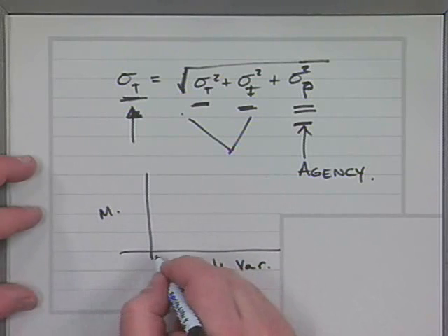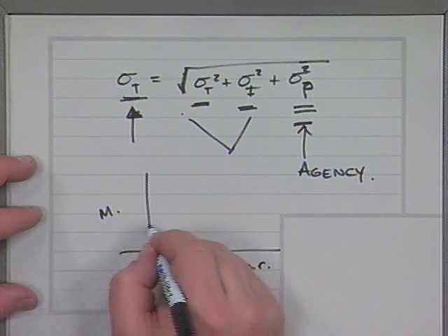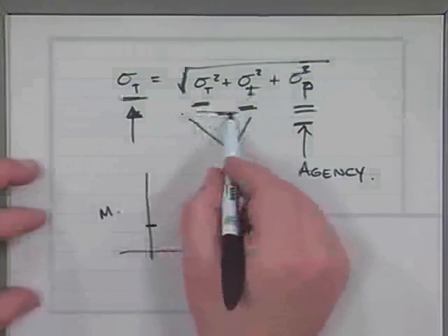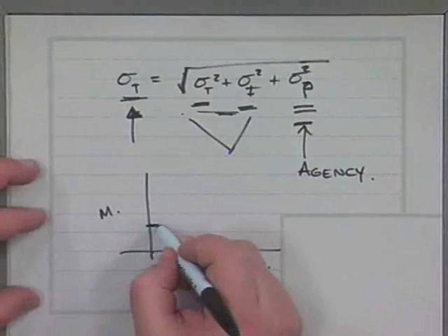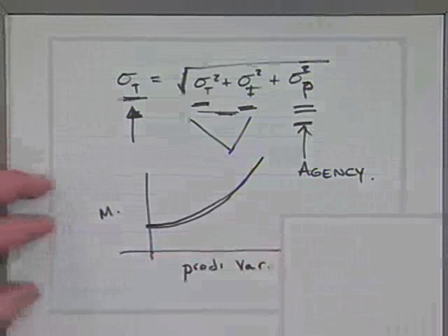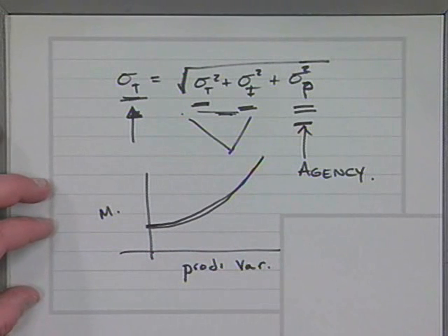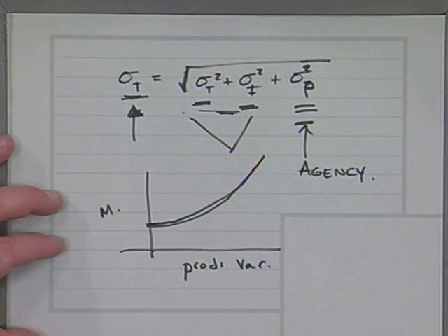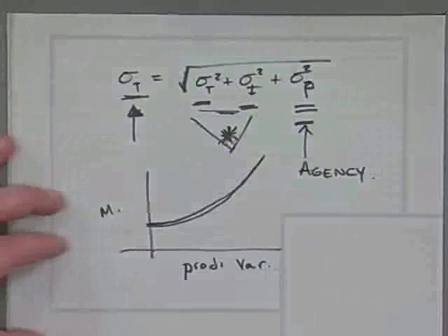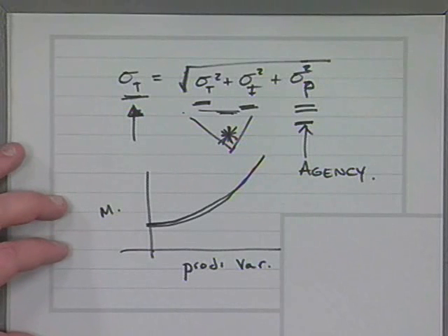You could have zero production variability, but you're still going to have a measured variability because there's variability in these other processes. And what you would find is a graph that looks something like this. You want to make sure that they're not setting the specifications so low that you're measuring the variation due to the inherent variability and the testing variability.